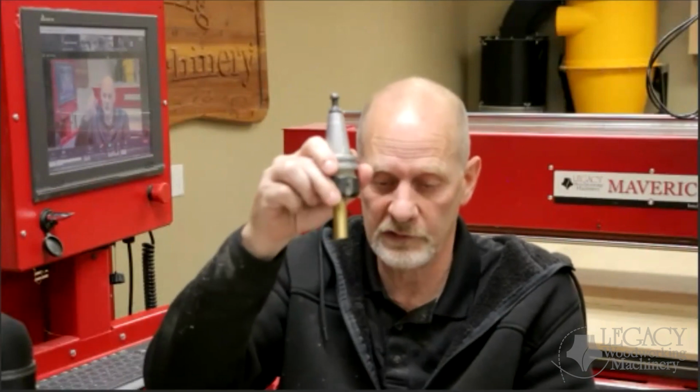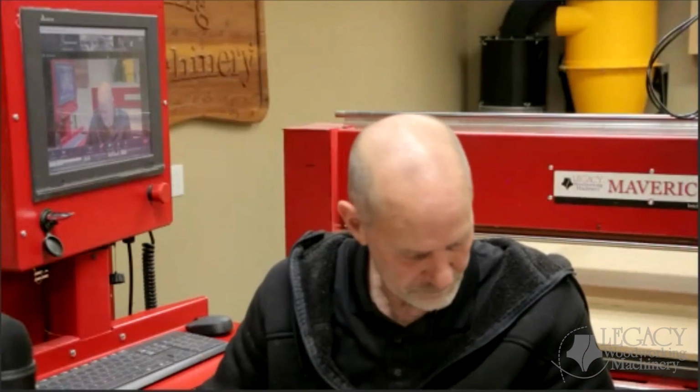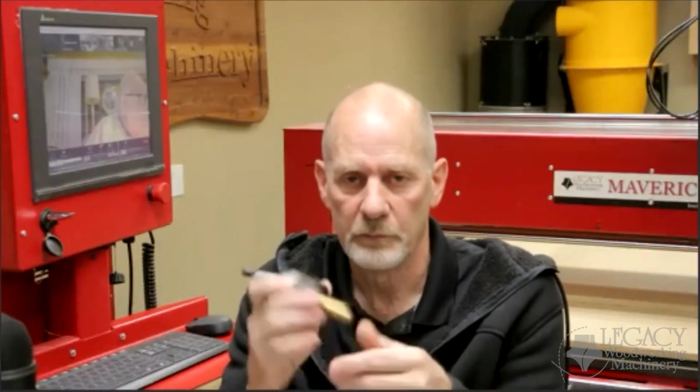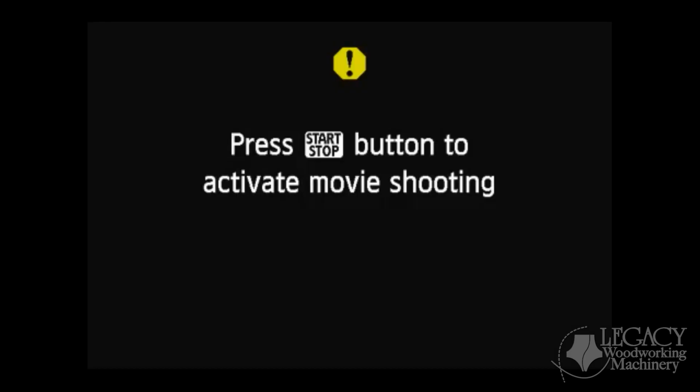Personally, I use this little 1/2 inch dummy tool as my setup tool because it doesn't have any cutting surface on it. It's flat. So it treats the Smart Tool pad real carefully. And I just use this as tool number like 9 or 10. And I also have one with the laser in it as well. And so I use it for like tool number 8 and 9 or 9 and 10 or whatever I want. I never put it in my tool clips. But that's what I use for my touch offs because it's very blunt, it's flat, and it's going to land perfectly. What material is that?